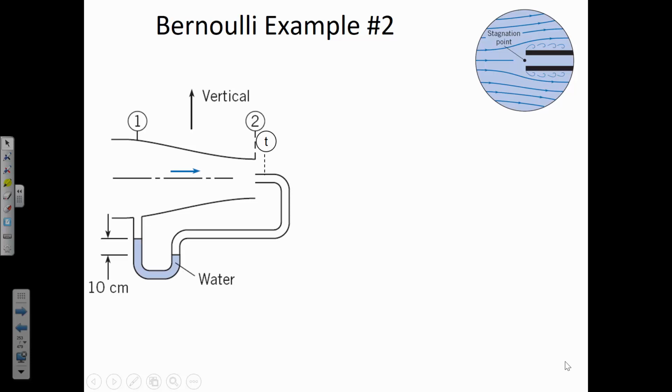But what you'll see is that the opening at the wide section isn't intercepting the flow, whereas the opening at the narrow section is intercepting the flow. So not only is it measuring a pressure difference, but this opening that the streamlines are dead-ending at is also getting a relative indication of how much velocity there is at that secondary location.